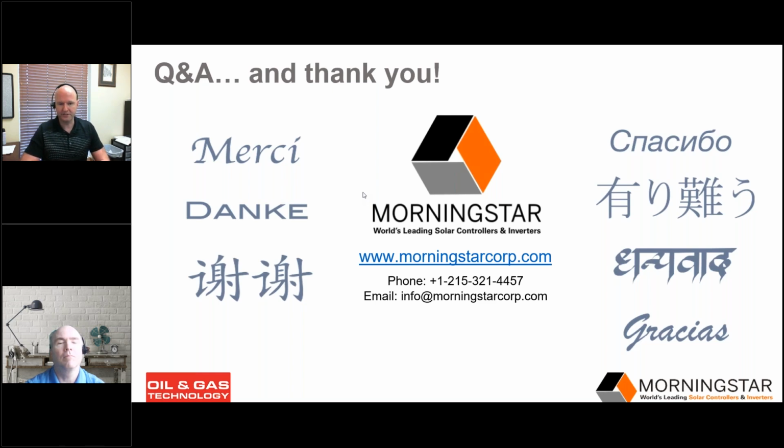What I would say is when you get into the finer points of engineering, with our products, we have power and efficiency curves available. If we're given a specific PV capacity and the operating voltages and battery voltages, we can very accurately determine the operating point of that controller and therefore its efficiency and the amount of heat that would be generated by that product in operation.